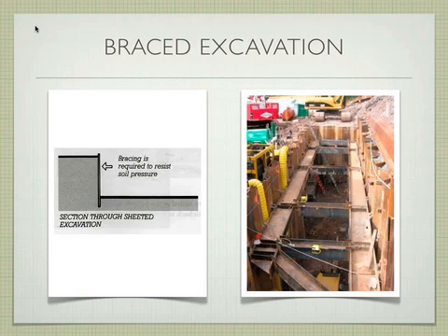But let's say you're digging somewhere in a city, right, in between two other buildings, right, and you kind of need to excavate straight down. If you want to do that, you don't have the space on the land to be able to do that benched excavation. So instead, you're going to be stuck with some kind of a braced excavation. Okay?